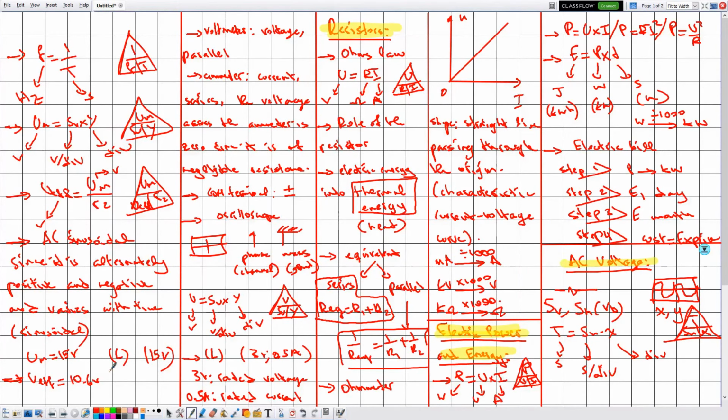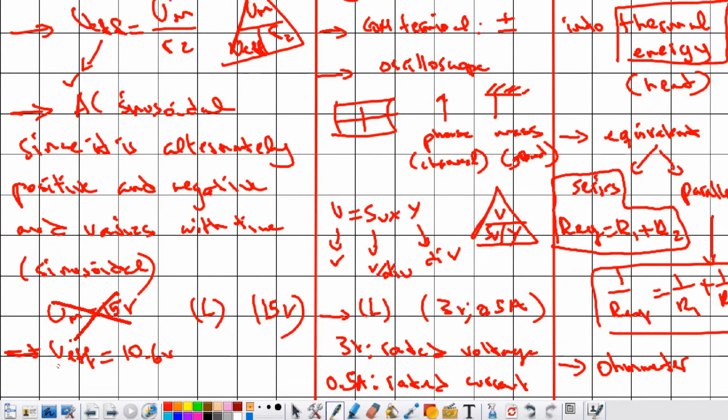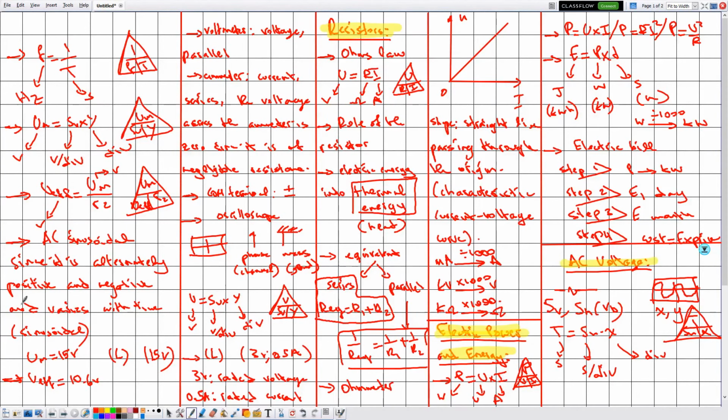To discuss the functioning of the lamp, we need to compare the applied voltage to the rated voltage, but here the applied voltage is the effective voltage and not the maximum voltage, because it is the one that makes the effect. Even if you connect a voltmeter to the AC source, it measures the effective voltage.